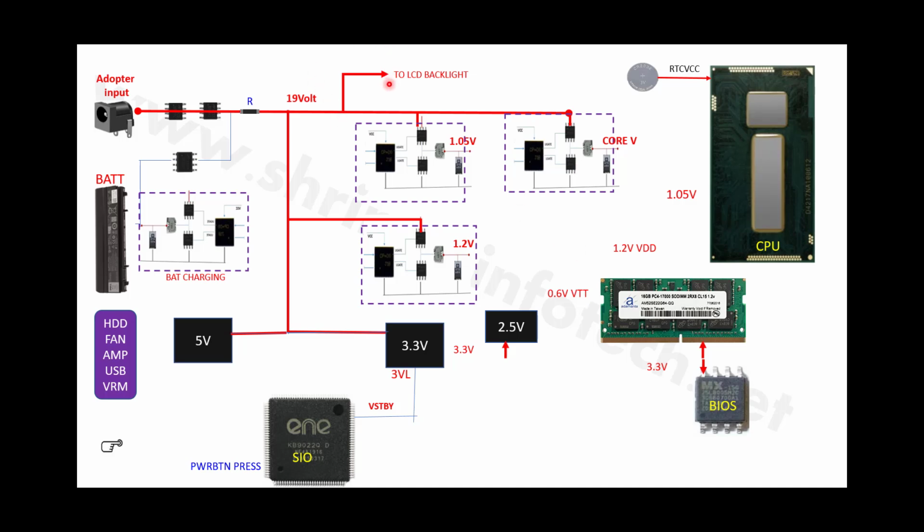Sometimes what happens is there is a short circuit on this side, like when I apply the power, the voltage gets shorted. Shorted means the voltage gets connected to the ground, that is called a short circuit. There are multiple ceramic capacitors across this positive terminal, so many capacitors are there, and one of the ceramic capacitors gets shorted due to circuit failure. So how to identify that short circuit, we are going to see.